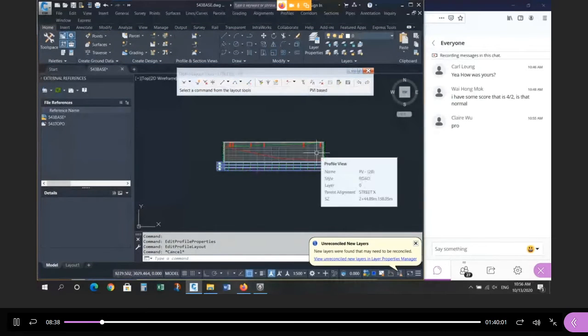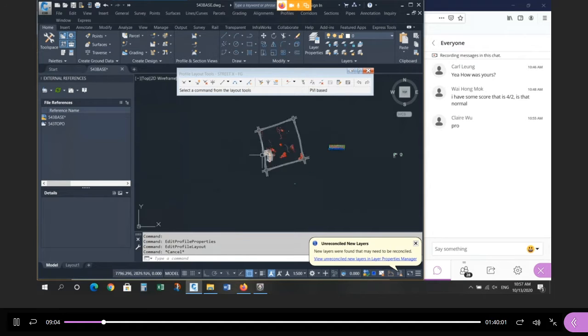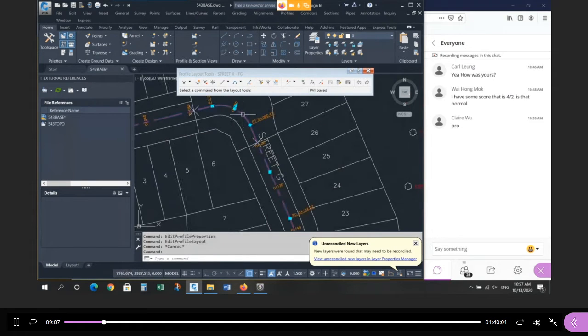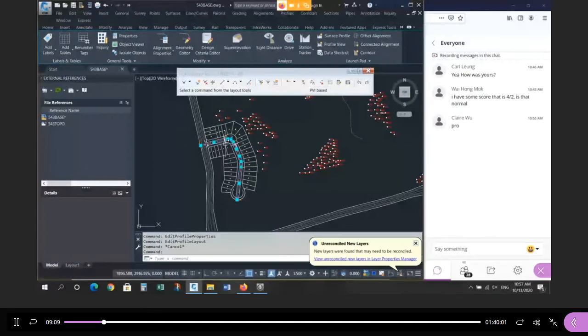Okay? And that's where we left off last week. And what I want to continue with today is the discussion now. What we're working toward is creating a corridor model. And the corridor model requires 3 parts. The 3 parts that are required to build any corridor, if you remember from highways, is you need to have the horizontal alignment, which we do. So you should all have a horizontal alignment now as part of assignment 2.